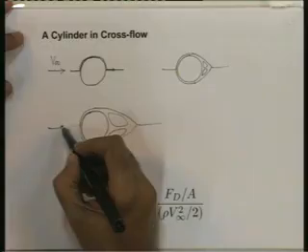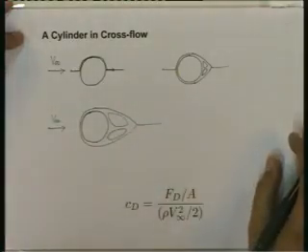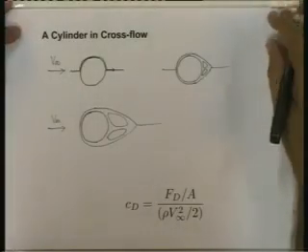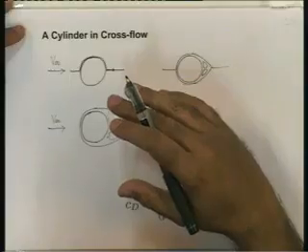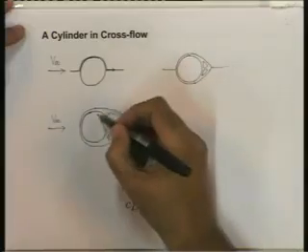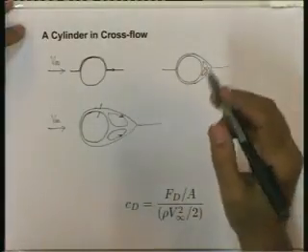Sometimes the boundary layer becomes turbulent after separation, sometimes it becomes turbulent before separation. So you may have a laminar boundary layer separating and then becoming turbulent, or a laminar boundary layer first becoming turbulent and then separating. When the flow separates and these eddies form, that particular part beyond the separation point is not really a boundary layer.